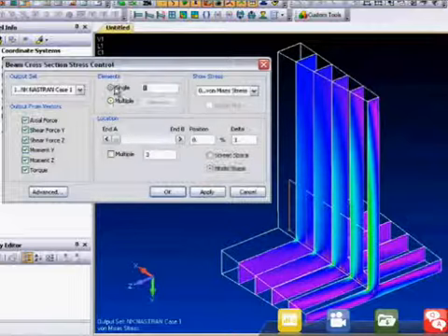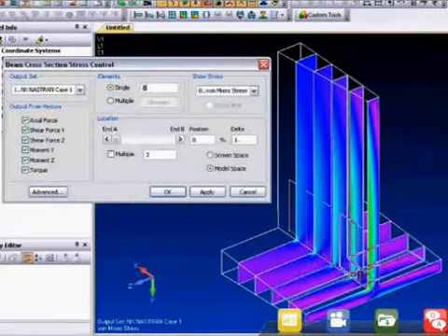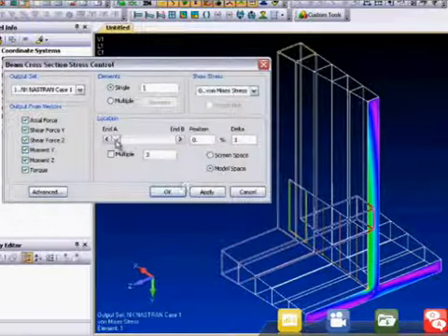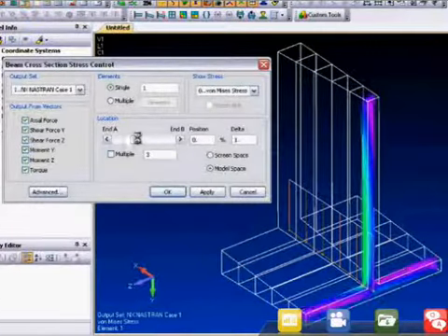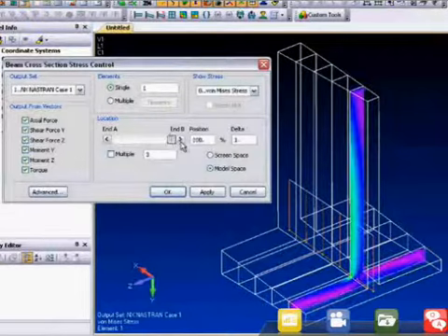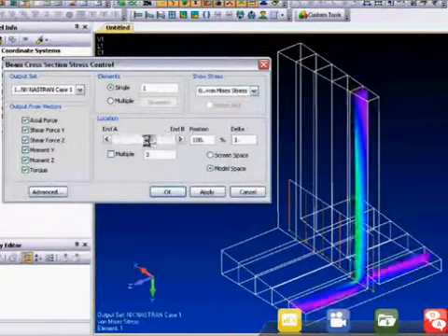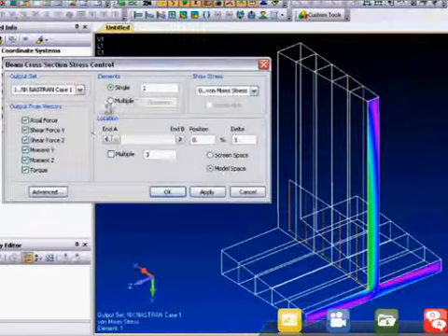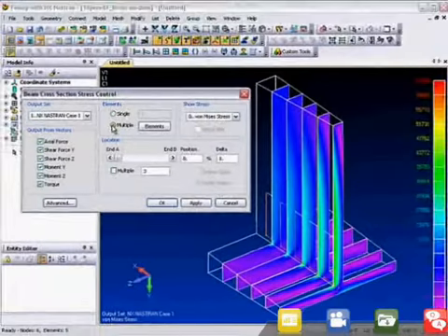For each element, you can also view multiple cross-section contours, or dynamically move the contoured cross-section up and down the beam for all selected elements. So, viewing results from beam elements, typically the most difficult elements to visualize easily, becomes much easier and quicker in FEMAP with the ability to view contours on beam.